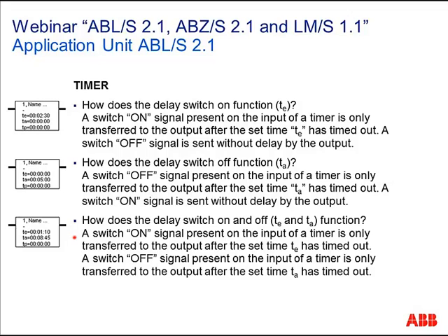Of course, you can combine both, like here on delay 1 minute 10 and off delay time 8 minutes 45. It means it receives on the input a value 1. Then the timer starts internally. After 1 minute 10, the 1 is sent to the KNX bus. When it receives the 0, after 8 minutes 45, the 0 is sent to KNX.